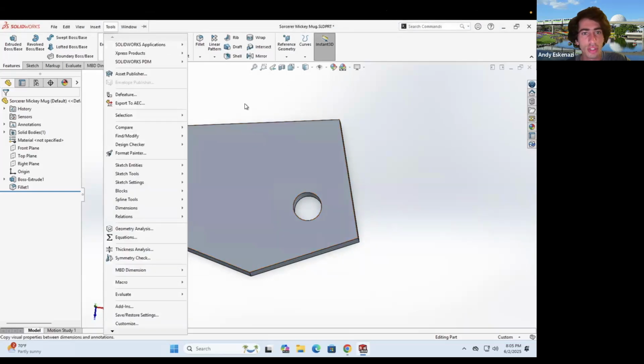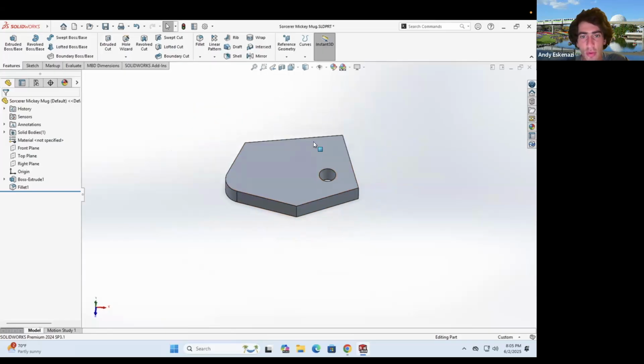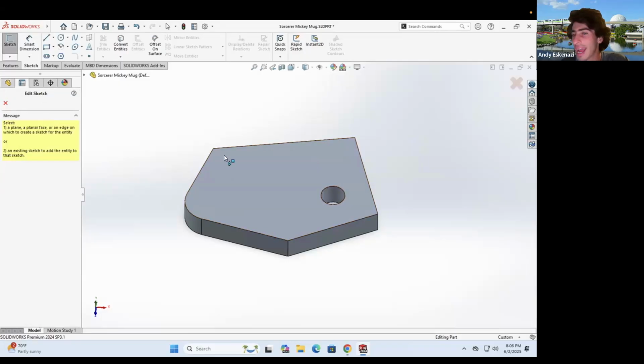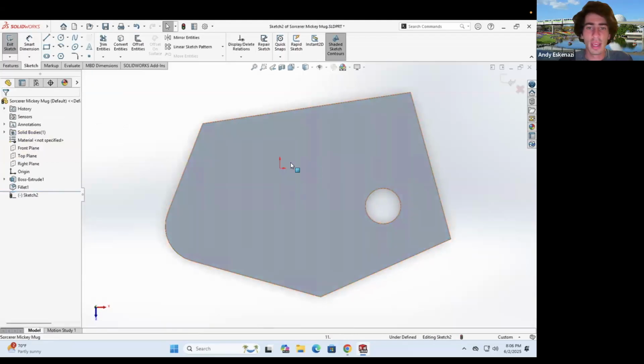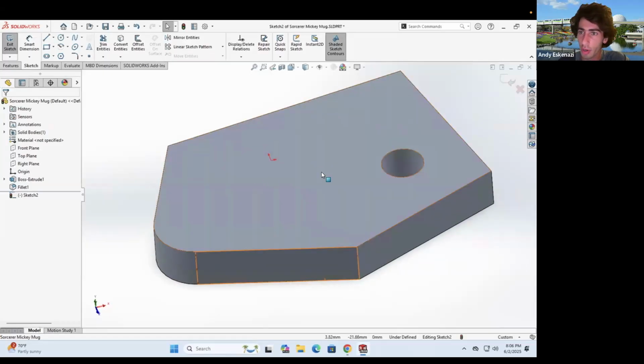That's an example. Another one that you could do is called extruded cut. To illustrate that one, let me show you another concept. In a similar way that, for instance, a cake, which was one of the very first demos that we would do in this class, has multiple layers, right? So I can go here to sketch, and now it's going to ask you again to select a plane. If you go to the little triangle, you could select again the very first three planes that we were given the choice of at the beginning, or I can just say, all right, I want this face right here. And again, the origin appears there. That's consistent with the origin that we originally used. By the way, the first plane that we used was this face right here. Now we are working on this face.